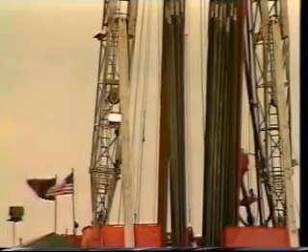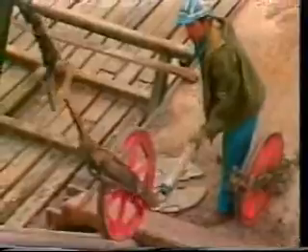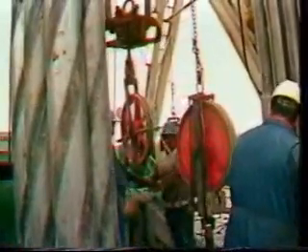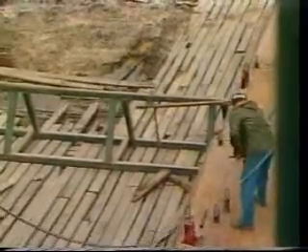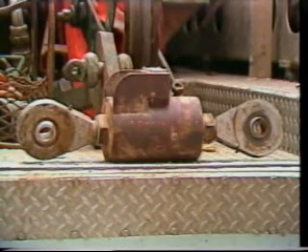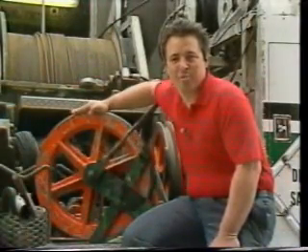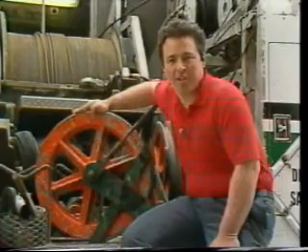Once the drill pipe is clear of the rotary table, the next step is to rig up. This procedure includes hanging the sheave wheels, threading the cable through under the bottom wheel and over the top wheel, then attaching the cable head to the uppermost tool and raising the tool string. A cable tension gauge is always used and may be attached to either the upper or lower sheave wheel. It is important to remember that these sheave wheels will be points of maximum stress during the logging run.